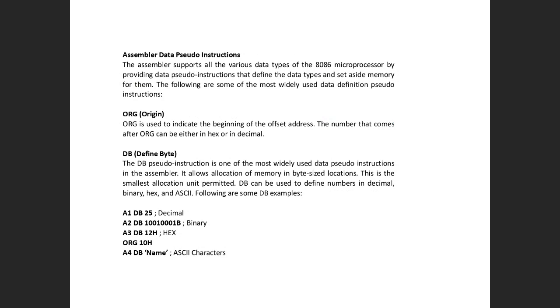Okay, so sometimes we use some pseudo-instructions. ORG stands for origin or beginning of something; we'll use more examples. And DB stands for define byte. The DB pseudo-instruction is the most widely used data pseudo-instruction in the assembler. It allows allocation of memory in byte size, or 8-bit. This is the smallest allocation unit permitted, and DB can be used to define numbers in decimal, hexadecimal, or as ASCII code. Okay, look here.